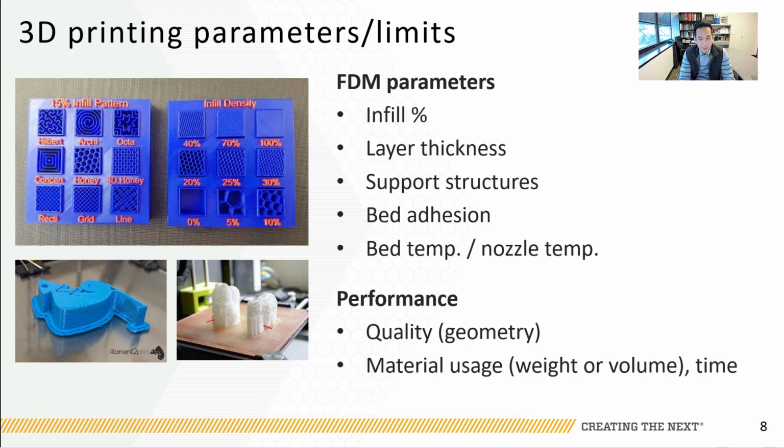There also are some performance differences in terms of material usage. As you can tell with the infill density changing, you might be depositing more material, and whether or not that is important is dependent on what your objectives are for your particular design. We also have time changes, so the more material you're putting down, generally the more time it's going to take.